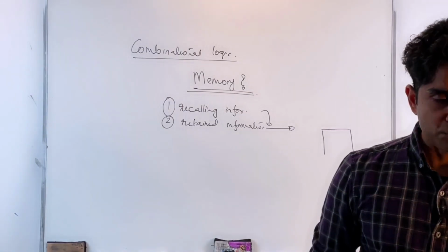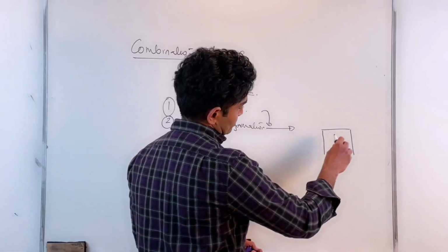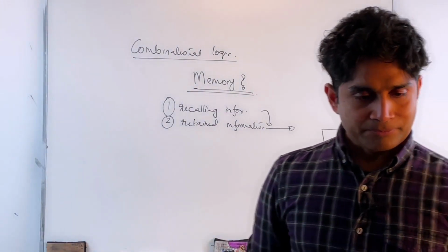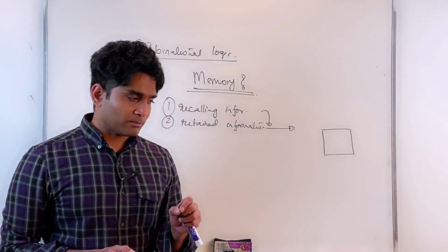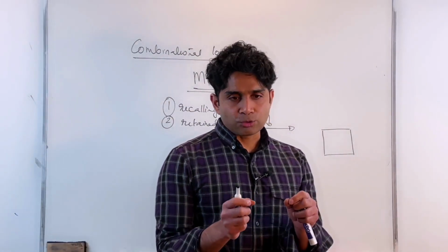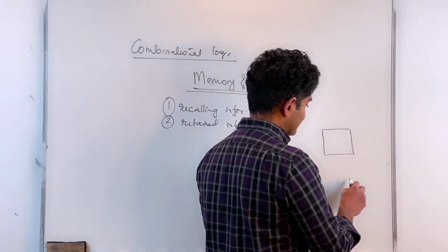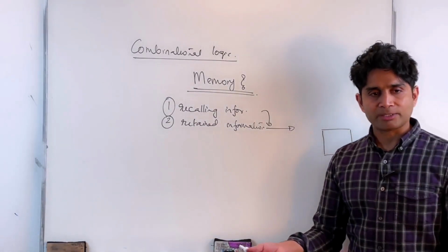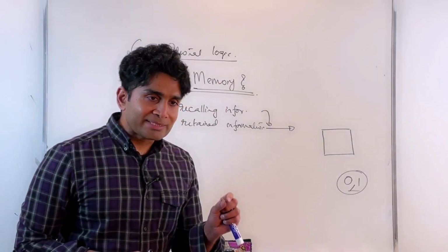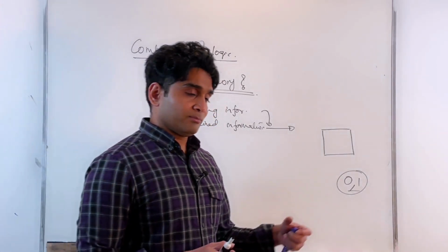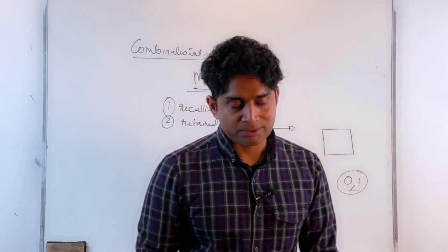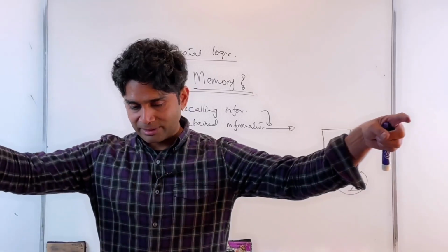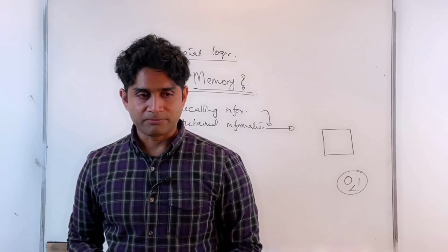So source, as in, I'm the source here. So in other words, let's now talk about memory at the very fundamental level. The beauty about digital systems that work on binary is that if I can construct a unit that can store a single bit of information, right? Because my information, when I'm talking about this class, it's all zeros and ones. Zero is as good as one, right? It's not like zero has less priority than one. Zero and one have equal priority. Basically, that's information. And if I'm able to store a single bit of information in my unit, then through a modular approach, if I want to make it into an n-bit memory storage, all I have to do is copy and paste that particular module that can store one bit n times. And now I have basically an n-bit storage element, right? So a very modular approach.